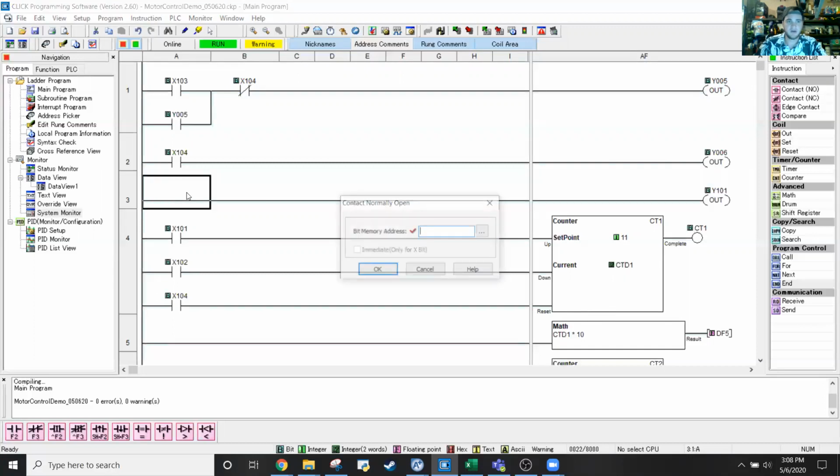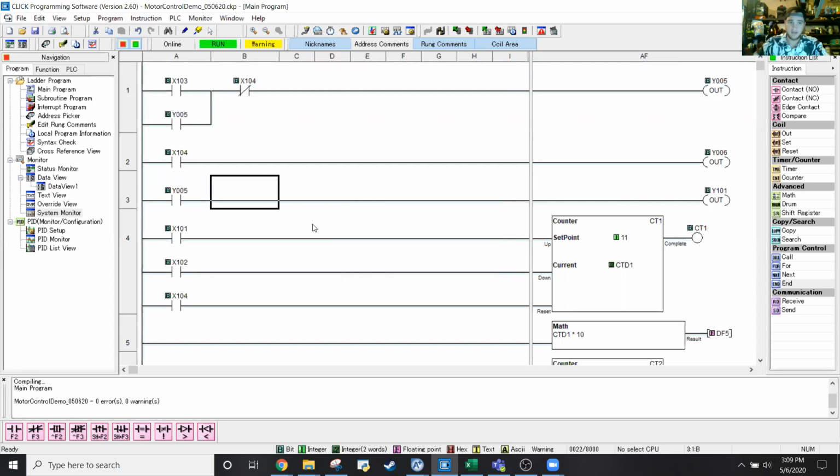So best practice is to have something engaging that bit. And like I said, ideally you would have a physical switch, like a toggle switch, where the operator has to hit that switch, and that engages the contactor. And then they also hit the button, and that starts the motor. We have 4 buttons on this panel, so we're just limited on the total amount of user inputs that are available, and so.